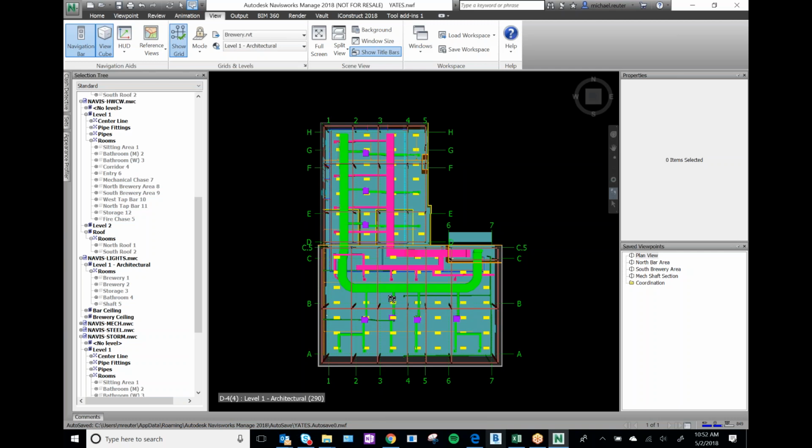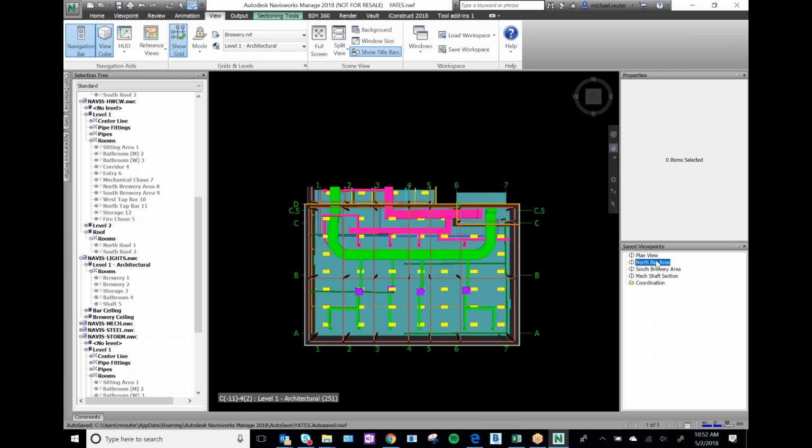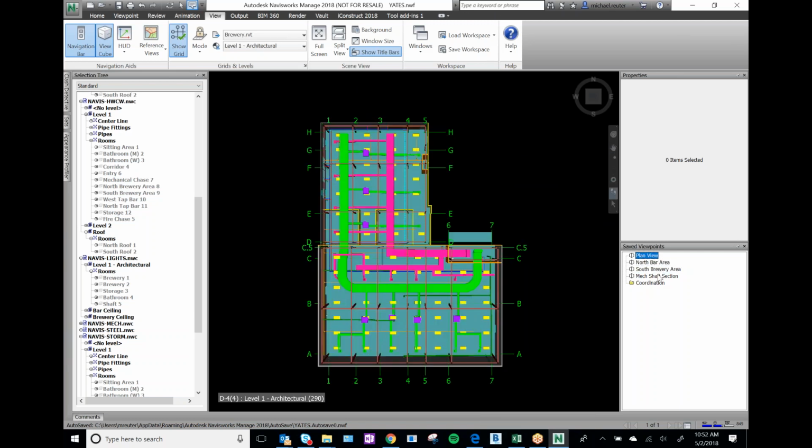So I like doing it because, like I said at the beginning, I like having no more, no less information than I need, exactly what I need. And so that's why I like building off the floor plan. There are sometimes where you can't do that, like maybe you're working on an auditorium that has an atrium in the middle. That's fine. That's why you create these sections, so that if you have clashes at those, you click on that view first, and then you create the view from that section.